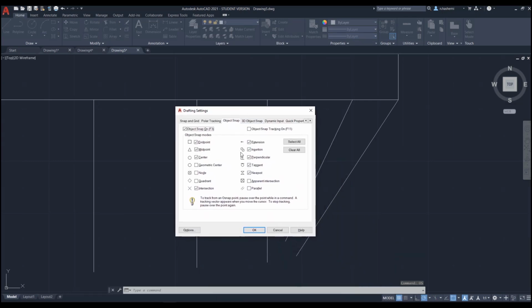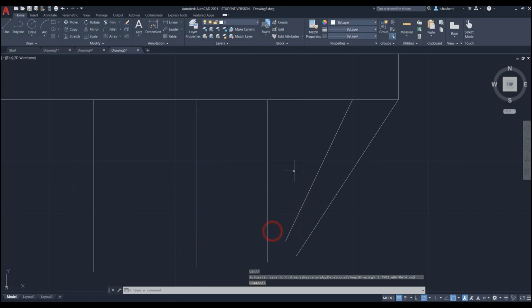So make sure to memorize these symbols, okay? You will probably have them in your tests. Now let's go into the line command, use the line tool. And when I move my cursor over a line, in the gray box attached to my cursor, you can see that it shows me it is nearest right now. If I pick this one and go over this, you see it is showing that this is an end point, or it is a midpoint.